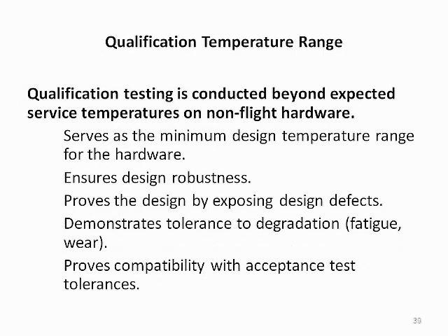Qualification testing is conducted at temperature levels well beyond the expected service temperatures and is performed on non-flight hardware. This wider range serves as the minimum temperature range to which the hardware must be designed. Designing and testing a unit to this wider range ensures design robustness, proves the design by exposing any design defects, demonstrates tolerance to degradation due to fatigue and wear, and proves compatibility with acceptance test temperature control tolerances.